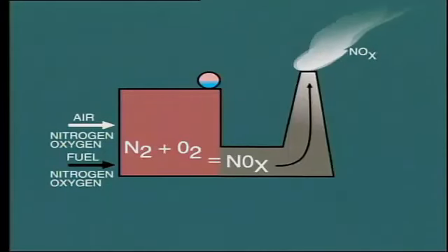NOx includes various nitrogen oxides which are formed during the combustion process by high temperature reaction between nitrogen and free oxygen. Both of these elements are present in the combustion air, and small quantities may also be contained in the fuel. When discharged to atmosphere, NOx causes irritation to the eyes and throat and may even cause respiratory problems in certain individuals. It is also thought that NOx affects the ozone layer and also contributes to the formation of smog.